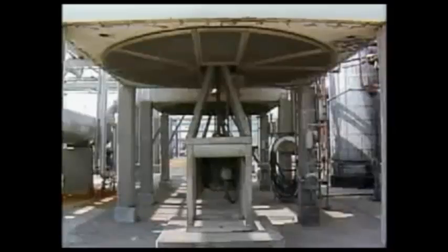During operation, the fluid being cooled passes through the tubes. The fluid transfers heat to the tubes by conduction and convection. Some of this heat is then transferred through the tubes and into the fins by conduction. From there, heat in the tubes and the fins is transferred by conduction and convection to the surrounding air. To increase the amount of heat transferred to the air, the fans in the cooler can be started. This increases the airflow through the cooler, which increases the amount of heat that is transferred by convection to the surrounding air.